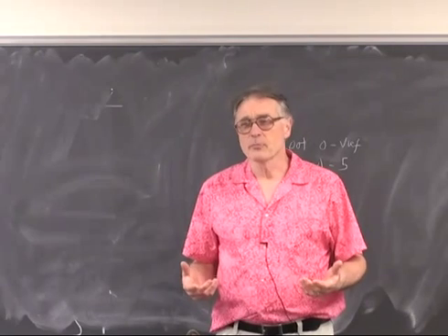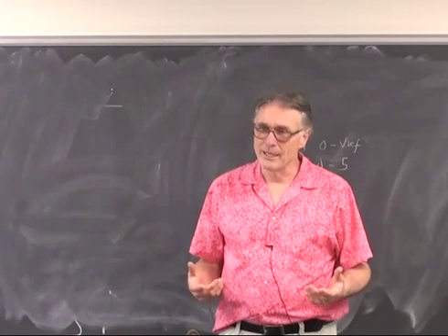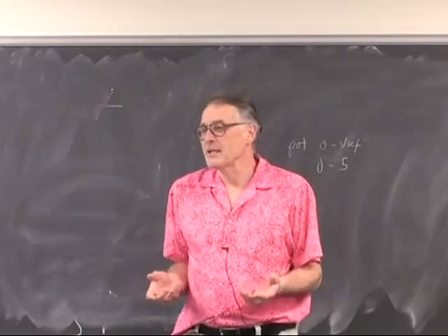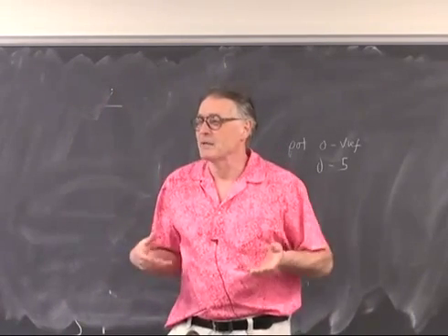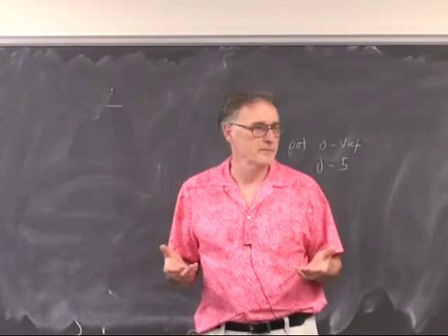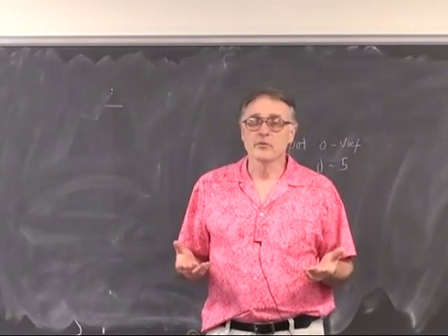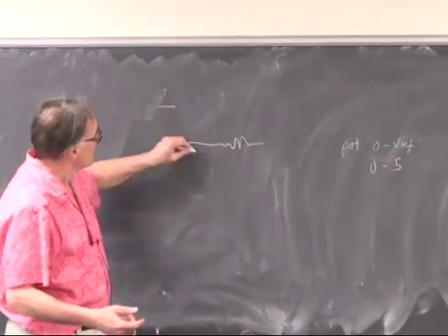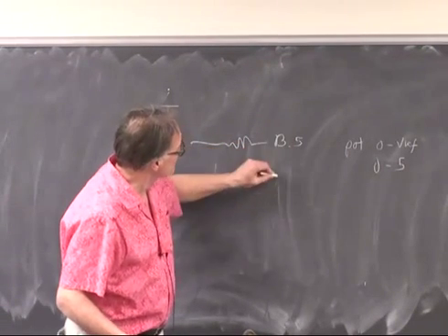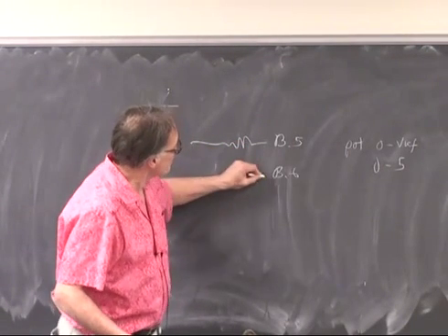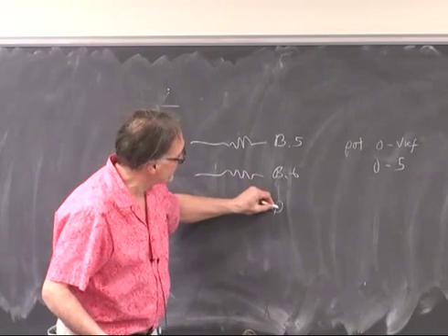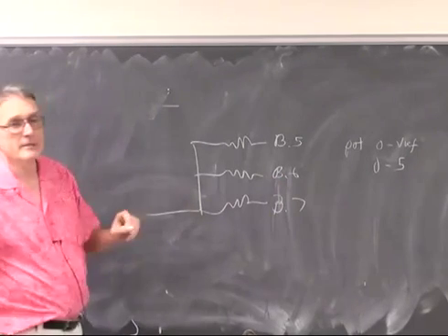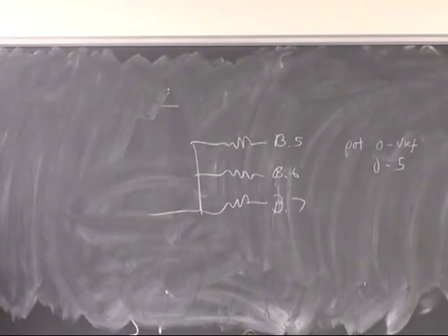The problem is that the programmer does not go into high impedance state when it is not programming. It goes into kind of a medium impedance state, like a 10K or so output impedance. That means that the three resistors corresponding to the three resistance measurement channels never get disconnected completely, and so the resistance measuring isn't auto-selectable.